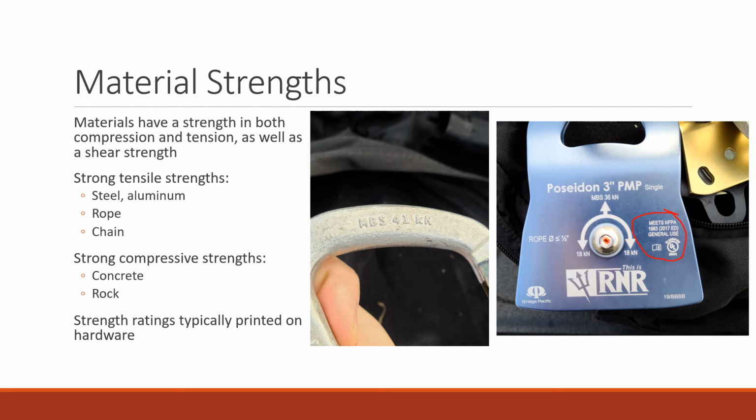General generally means it's good for a large rope system with lots of load, and there's a higher safety factor generally involved in a G system. As soon as you go down to T, the minimum breaking strength that's required comes down pretty significantly, but it's still crazy high. We're looking at component breaking strength still greater than 10 kilonewtons each, and it's all going to be crazy strong. Don't worry too much about it, but at least it's good to know about.